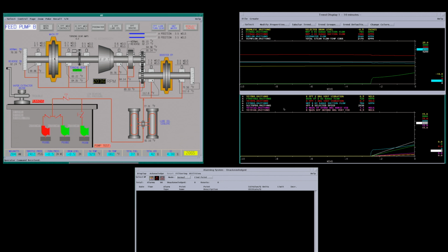You can also get cavitation from overdriving a pump. It's pumping out more water than it can on the curve. It starts making a really low pressure on the suction. You get small bubbles that'll collapse and make a lot of noise and do damage. They actually start eroding metal.